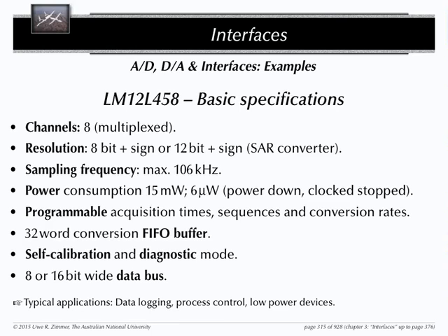Self-calibration in diagnostic mode is actually quite common for AD converters, since you need to be able to calibrate these devices. Those are quite sensitive. We talked last time about calibration voltages, reference voltages, which have to be set carefully. These devices have internal calibration circuitry, which can do this occasionally by itself. You have to actively trigger that, or you program it to do it regularly so and so often. You can also program it to do it after every conversion.